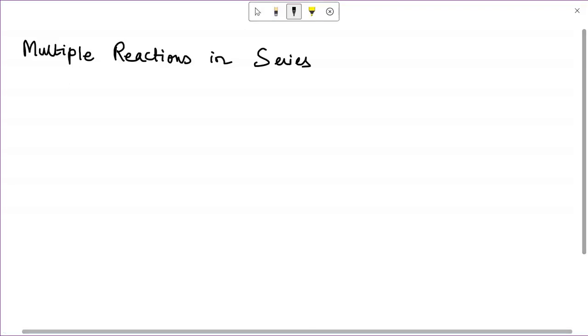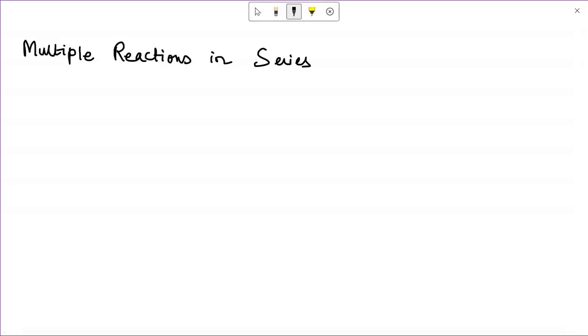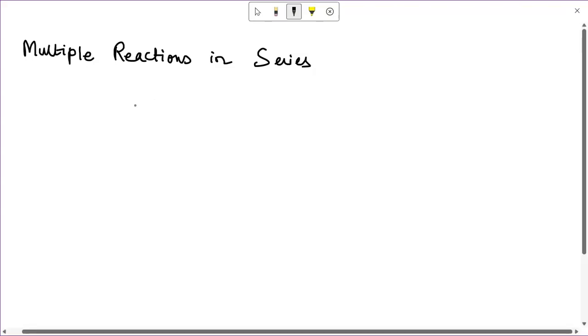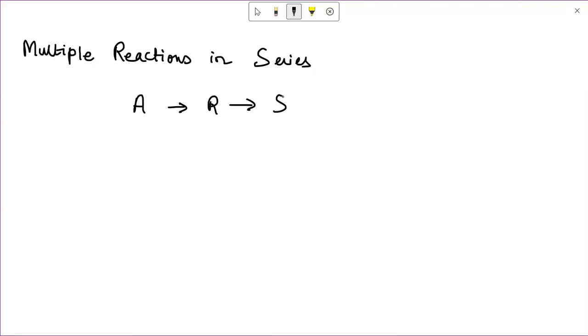Hi, in this video we are going to talk about multiple reactions in series. For irreversible reactions considered in a series configuration like A gives R gives S, the mixing of fluid of different composition is the main controlling factor for the formation of the intermediate.